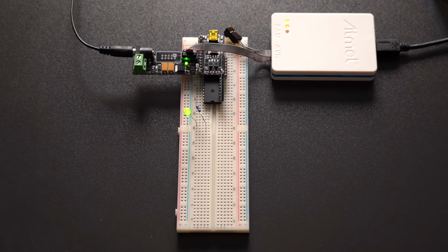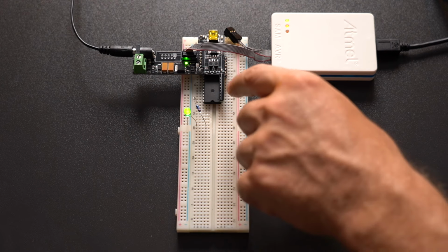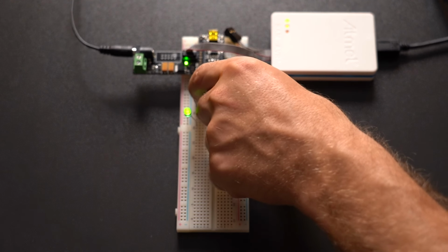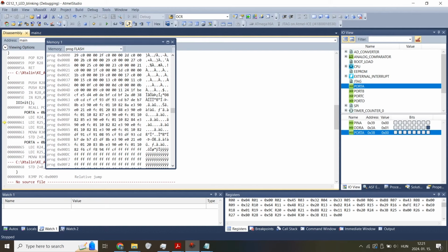It can also be an interesting game to test what happens if we pinch these pins with our finger and step 1 on the program. If we are lucky, we may experience some change in the value of the inputs. The reason for this is the processor's electronic structure and the fact that these pins are not connected to anywhere, so they are floating.